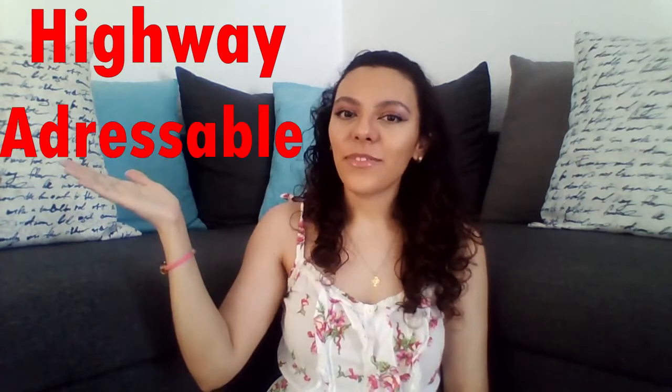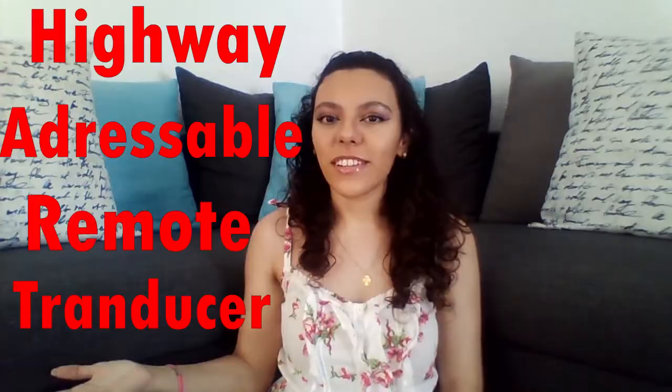So, the HART protocol. Highway Addressable Remote Transducer. It is a communication protocol widely used worldwide to send and receive digital information through an analog signal between smart devices and a control system. I mean that thanks to it, many sensor transmitters can communicate with controllers so that they can make the decisions that are required in a control system, whether it is to open a valve, start an engine, and even to be able to visualize the variables that you require in a computer.